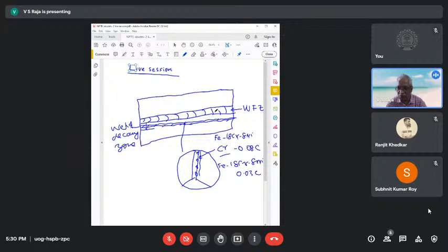For example, you're going to use 304L base metal, and you're going to use a 304L filler wire. If you use 316L base metal, you're going to use 316L filler wire or electrode. But of course, the 316L electrode will have a slightly different composition from this. So to make the point, whatever happens here in terms of composition has no role to play in weld decay. That's the point I wanted to make.